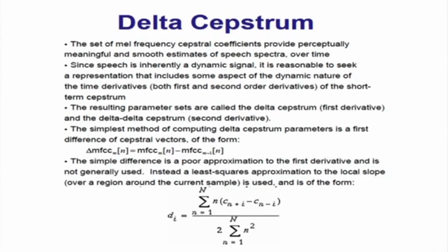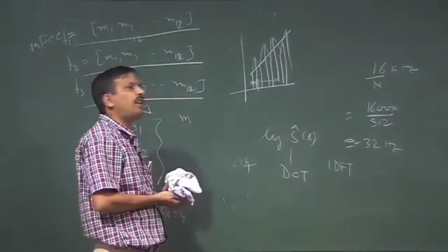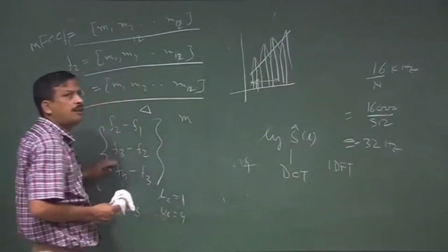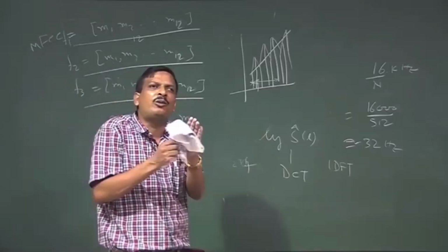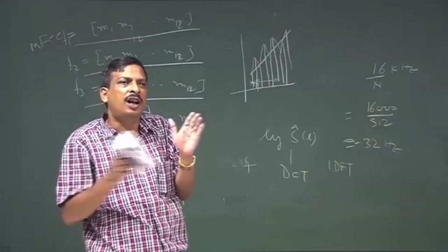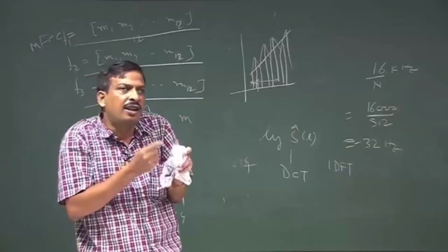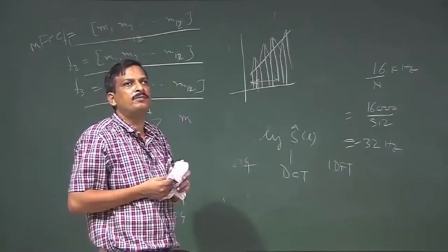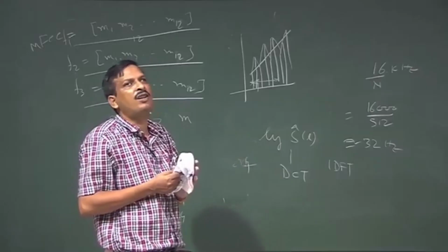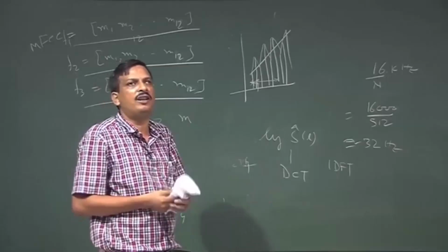To get the smooth movement of the formant. So, delta coefficient is not just the difference between the frames; we take several frames and calculate the average difference and then move the filter like a smoothing function, so that I can get the smooth variation of the formant frequency. Okay. So, that is called delta coefficient, and if I take the delta, the double delta coefficient.